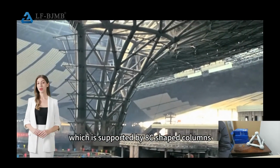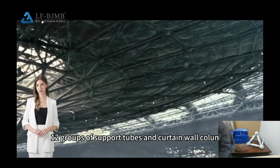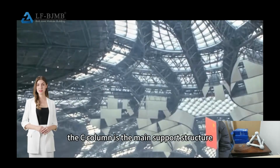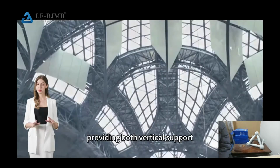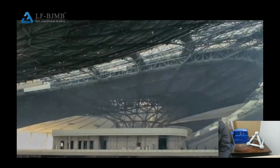8 C-shaped columns, 12 groups of support tubes and curtain wall columns, forming a large span roof of 180,000 square meters. The C column is the main support structure, and its unique shape and arrangement effectively transfers loads, providing both vertical support and horizontal stiffness.